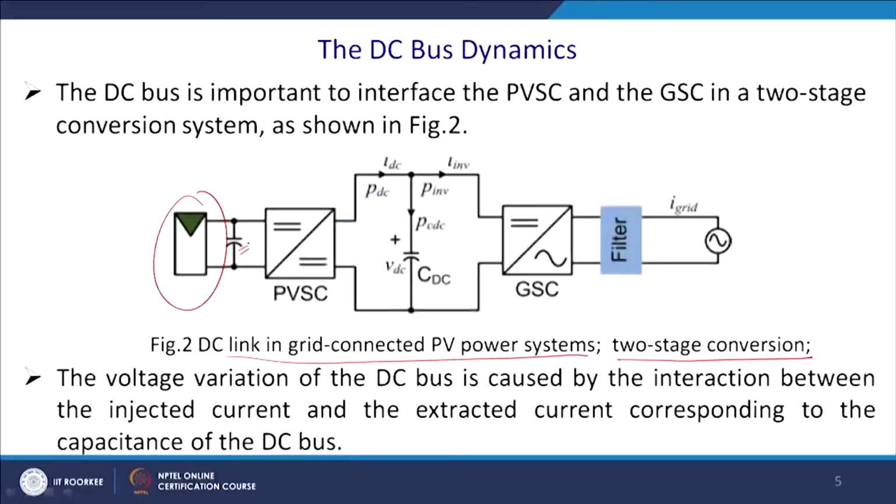And thereafter, in the same way, there might be an instantaneous mismatch between the power generation and the power supply, which has to be fed from or supplied into a storage element like a capacitor. Till this point it is DC, thereafter it will be the inverter current, and for this reason we require to model this capacitor rightly, so that it can sink that amount of current.